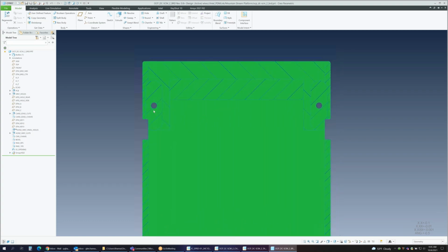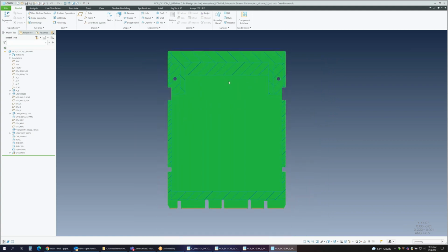For that reason, as a standoff on the bracket is sliding across the board in this area, we had an oblong or ob-round type KOZ here on the bottom. But we realized that if you're sliding the card into the host board, you need that KOZ on the other side as well. So we've changed this such that whether you're sliding it forwards or backwards, that standoff has enough room to not knock off components or hit surface traces or things like that that could be problematic. So that's one of the things we've added on the board itself.